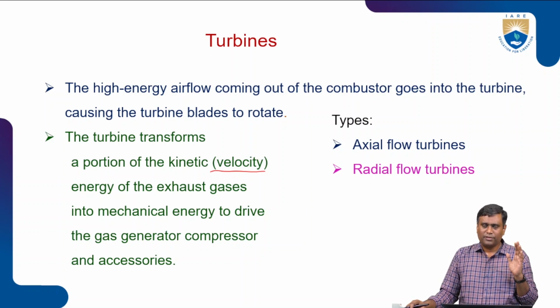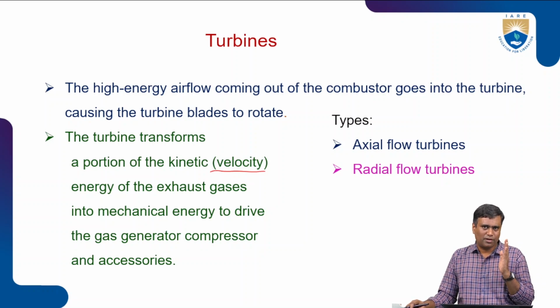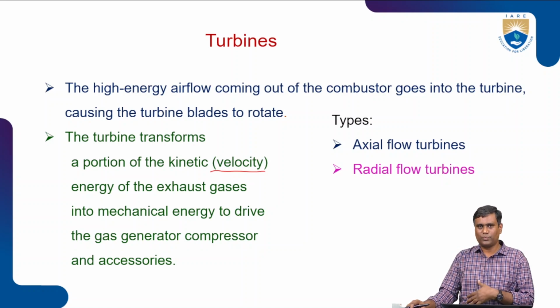So this is one component in the turbojet engine which actually requires advanced materials. Another part is the combustor, where the temperatures will be very high, and then immediately after that are the turbine blades, which are subjected to not only high temperature but mechanical stresses as well.